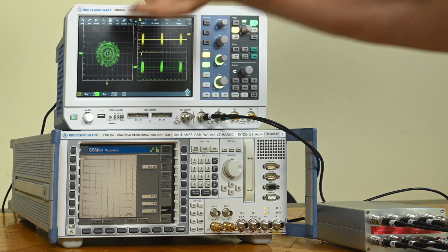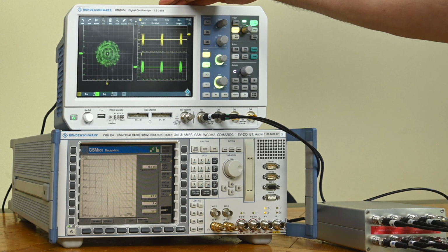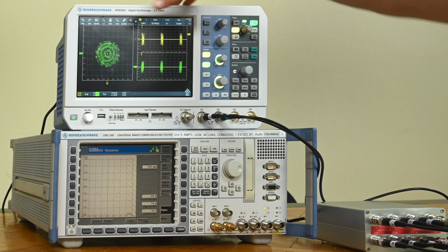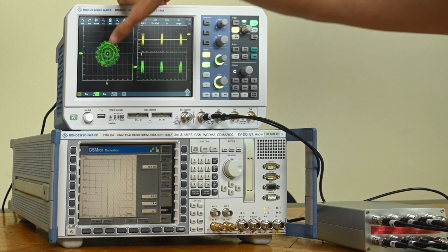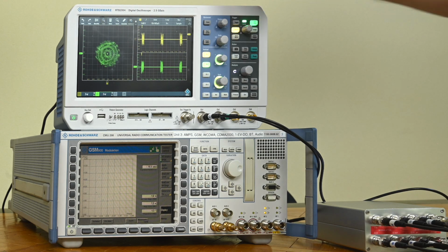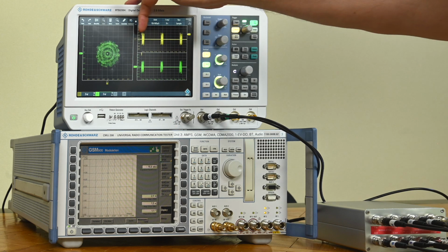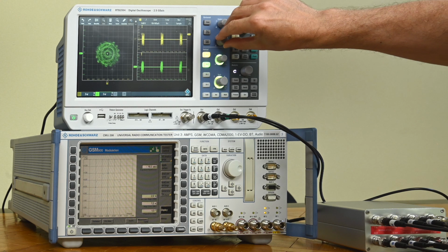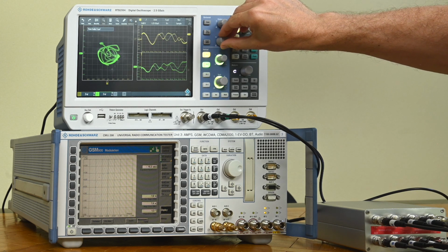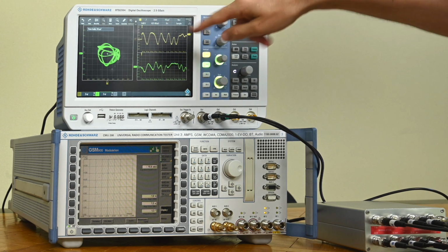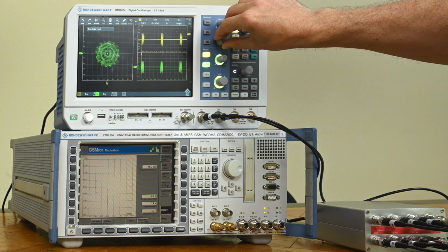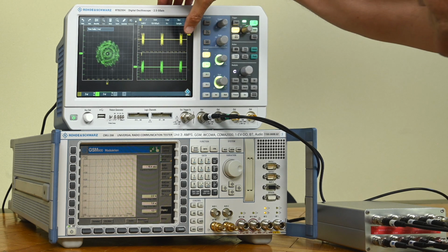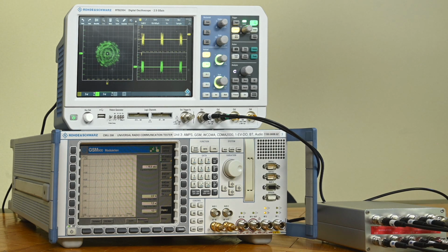We can see both the time domain and the XY domain at the same time. This is not triggered right now, in the sense that we see constellation points, so we're more or less seeing vectors. And we also see the signal is not continuous, we see bursts of signal. Again, this is a GSM signal, so we're probably seeing a time slot here, and if we make it bigger, yeah, these are IQ values that we actually see in this particular time slot. So every 4 milliseconds or so, we get this burst of signals with IQ modulation coming by.